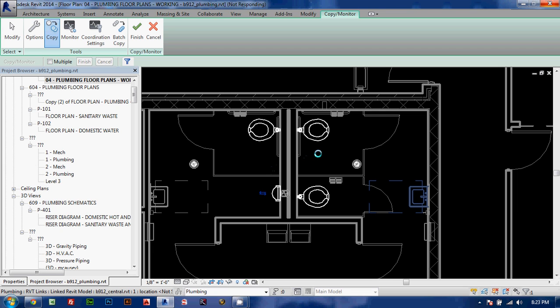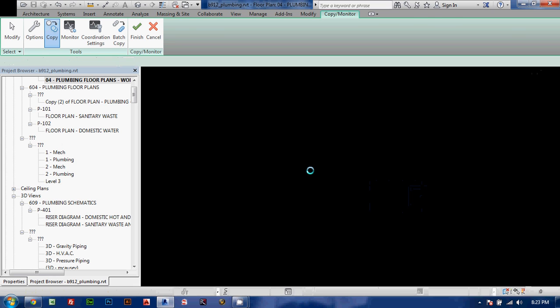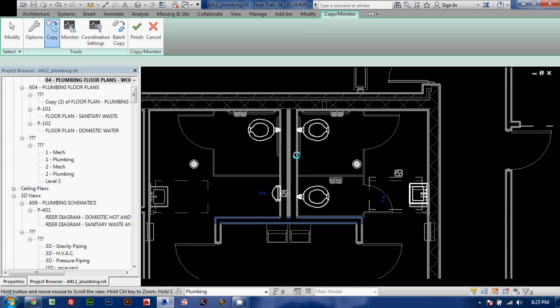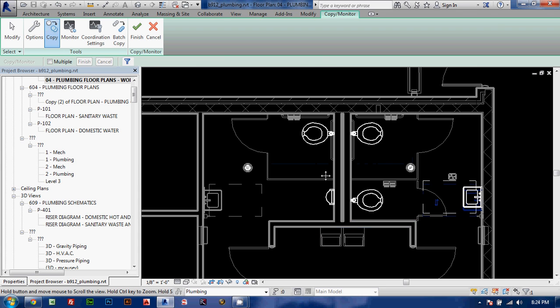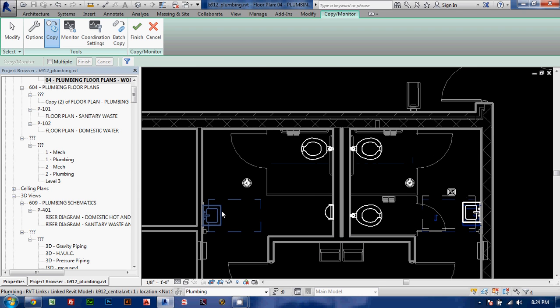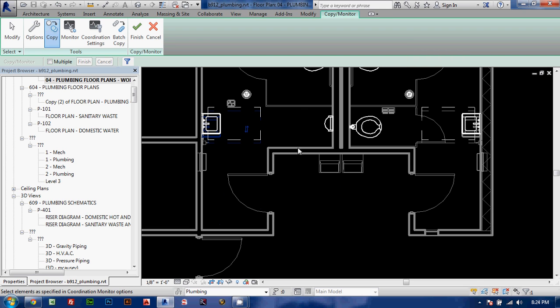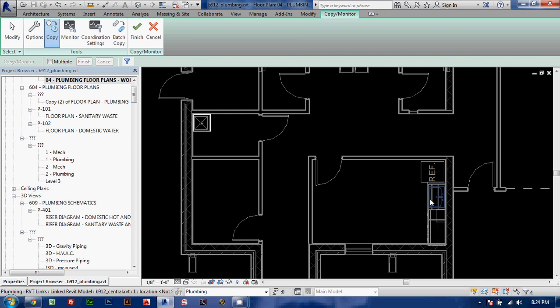It's really important. We had projects before where the plumbing fixtures changed enough that, when you're using slope piping, especially because slope piping in Revit is very, very finicky, if you were to change the location of one fixture, it might actually force the piping to go non-sloped, which is really, really annoying.